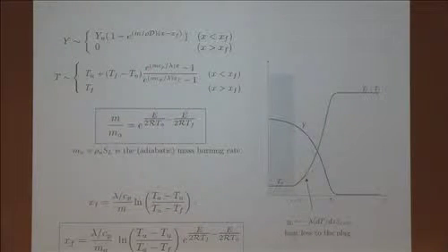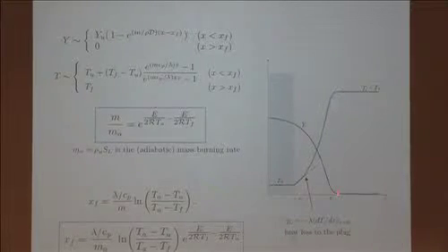If we satisfy all the jump relations, we obtain these two expressions which I have emphasized here in a box. So first of all, the temperature, as you see, increases from this value of Tu to some value Tf, which is less than Ta in general. It's smaller than the adiabatic temperature, clearly. And the concentration goes to 0 near xf.